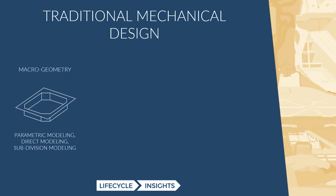So parametric modeling has been around for a while. Direct modeling, allowing you to push and pull geometry directly as opposed to working through features and parametrics, which is what you have with parametric modeling. And then subdivision modeling. That's a new one that has become more widespread recently, where you can progressively add controls. It's kind of like direct modeling, but with a little bit more organic control. So that's one of the levers that mechanical engineers can pull.